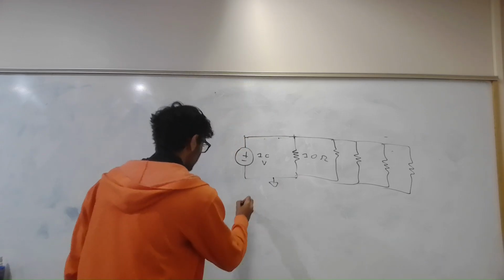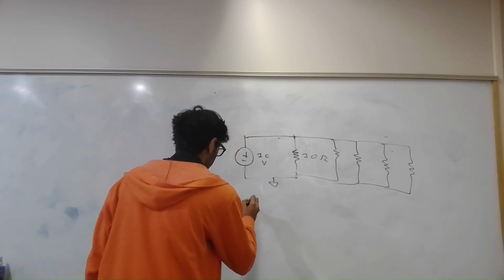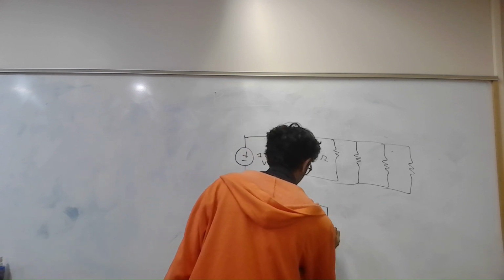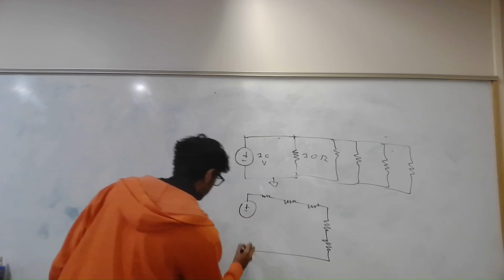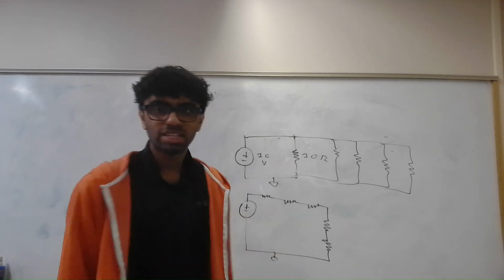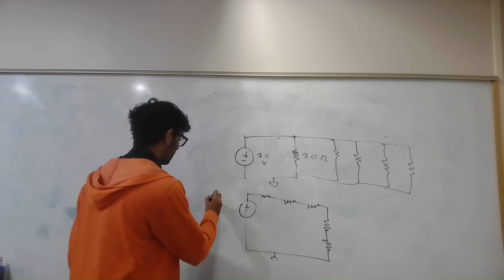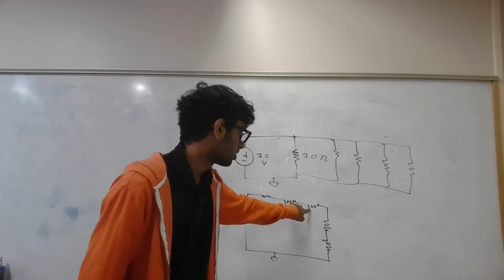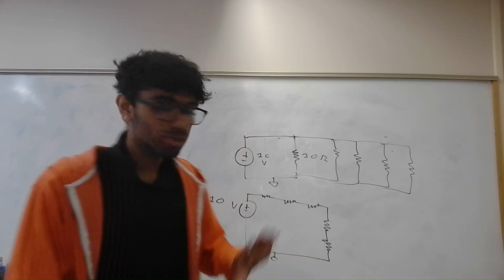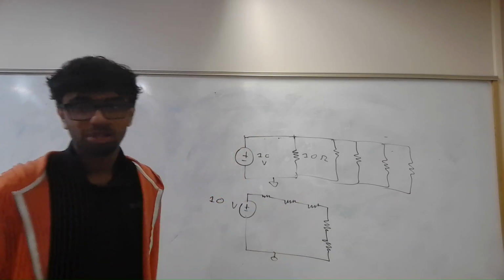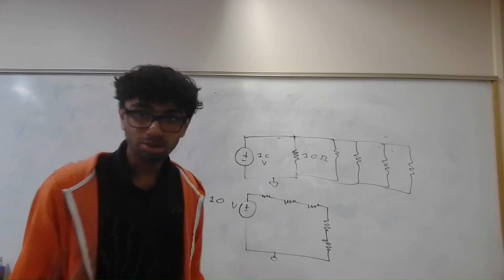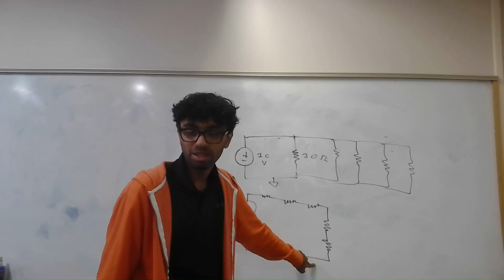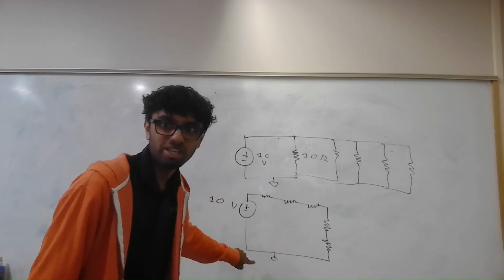Which kind of makes sense, because if I attach them all in series, then each one, if I do this, like I have a 10 volt battery like this, if I attach them like that, and this is a 10 volt battery, this one drops a little bit of the 10 volts, another little bit, another little bit, another little bit, another little bit, but all together, their drops have to add up to 10 volts because they're all in one loop. And if they don't add up to 10 volts, then that means I drop some voltage, I'm at like maybe 2 volts by the time I get to here. But I have to be at ground. I have to be at 0 volts.